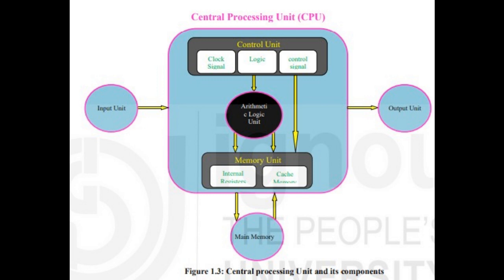Sometimes the execution of a program is required to be terminated abnormally due to the occurrence of certain errors or other conditions, like division by 0. Thus, there may be a need for a mechanism that can interrupt the execution of a sequence of instructions. This mechanism is known as an interrupt mechanism, which uses an interrupt signal. On occurrence of an interrupt signal, the CPU suspends the execution of the next instruction to be executed, though it completes the execution of the current instruction.